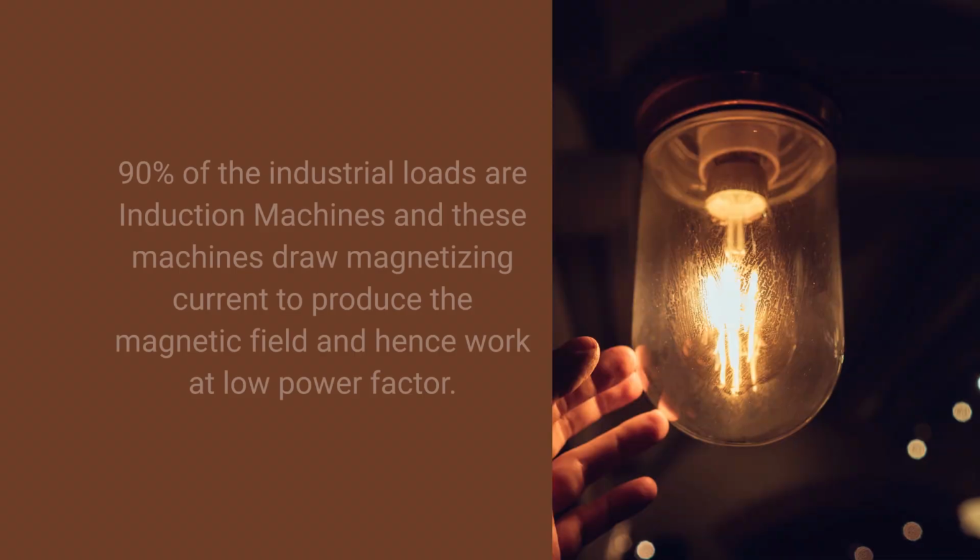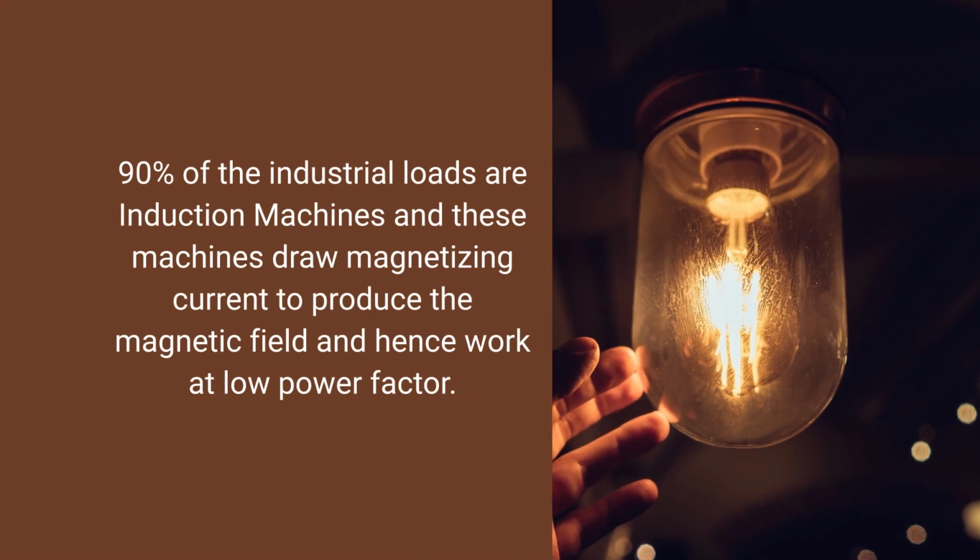So just now we are going to discuss what is the effect of inductive load on the power factor. As you know, 90% of the inductive load consists of induction machines. It may be single phase or three phase. Such machines draw magnetizing current to produce magnetic field and hence work at low power factor.